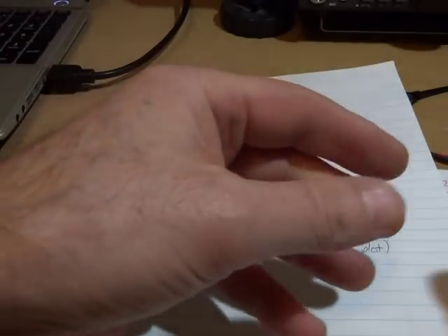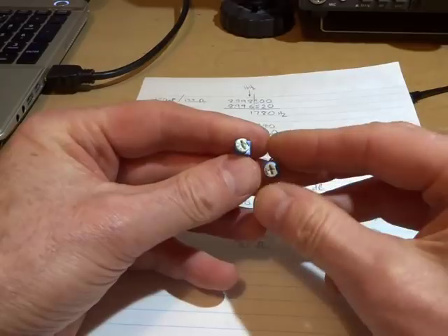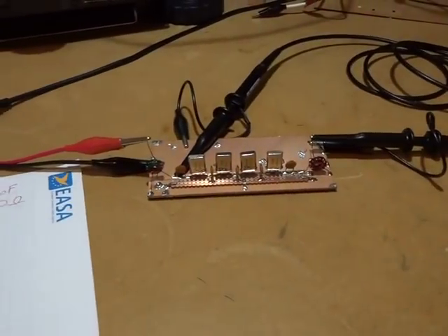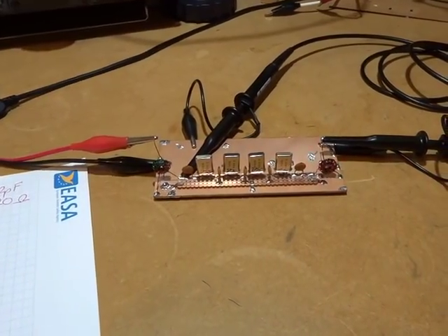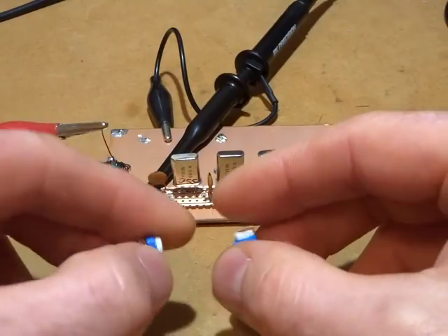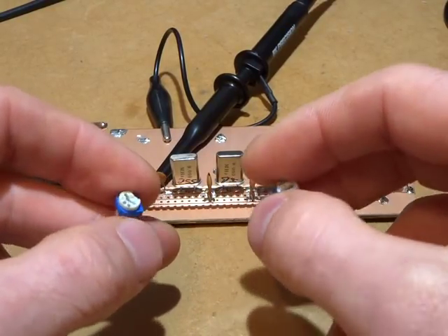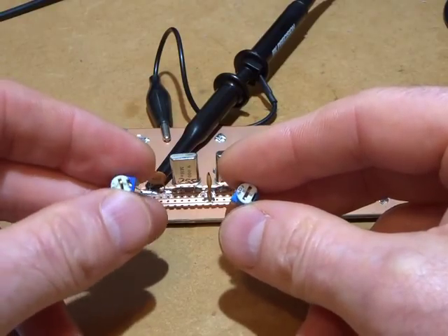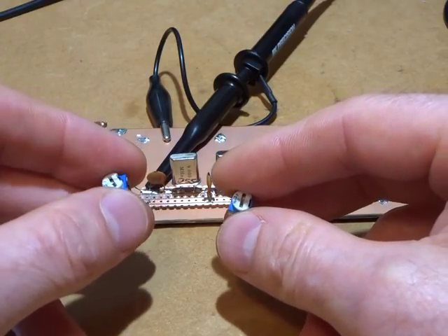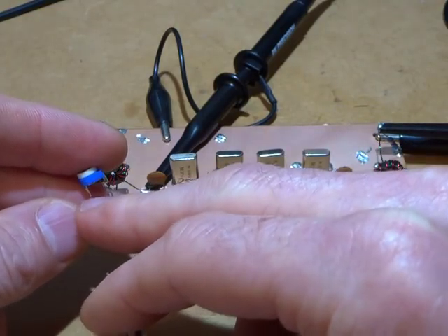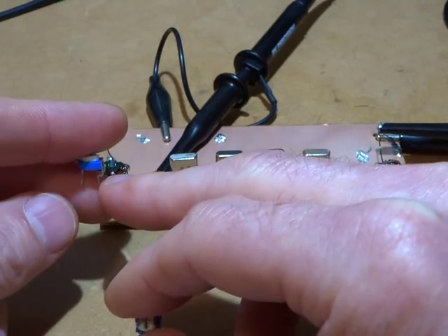So in the end I used a couple of variable resistors, and in fact if I just look over here, that is the test filter at the moment. In doing that final set of calculations, trying to work out what the ripple factor was, I used two variable resistors here. They're both 500 ohms. On the input, it was just a common leg and one of those legs, and it was left floating.